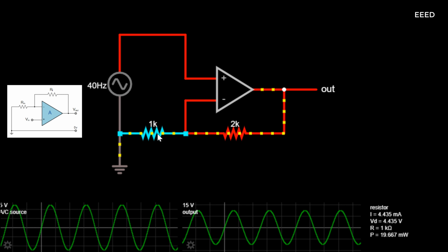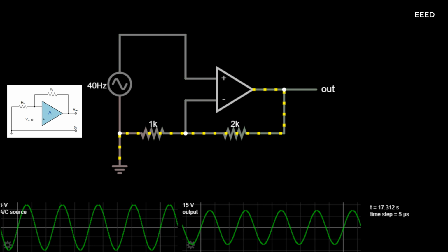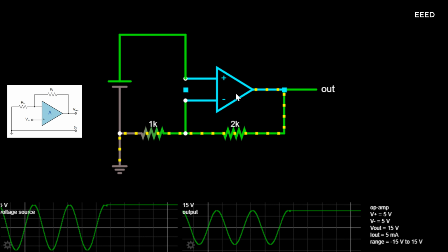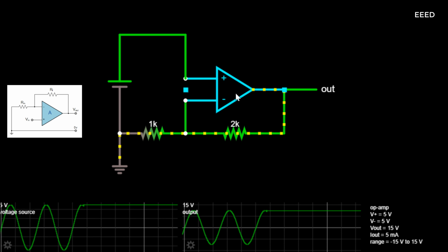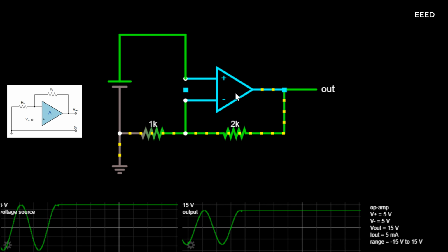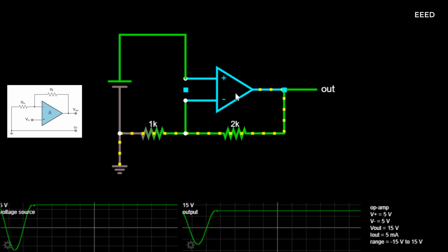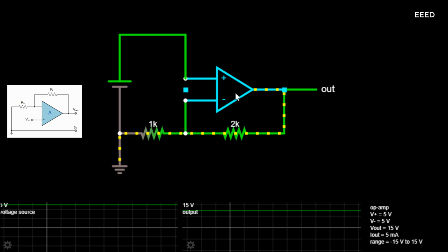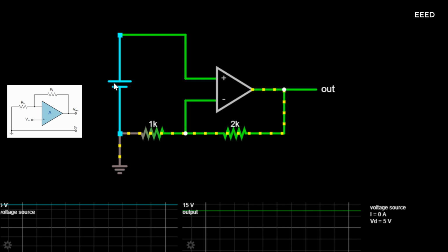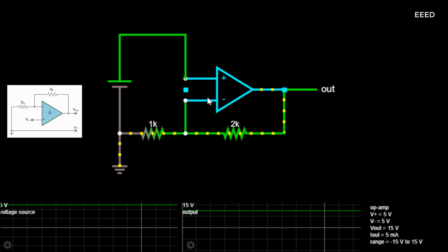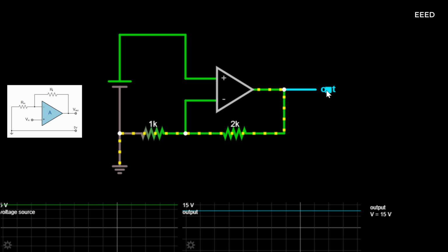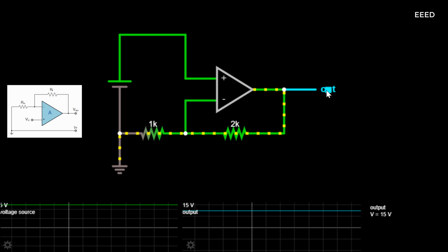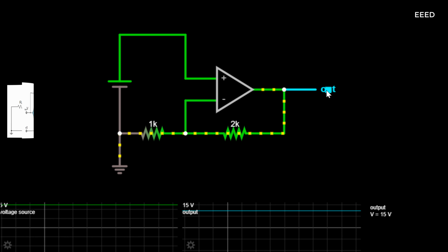This then makes the voltage follower circuit ideal as a unity gain buffer circuit because of its isolation properties. The advantage of the unity gain voltage follower is that it can be used when impedance matching or circuit isolation is more important than amplification, as it maintains the signal voltage. The input impedance of the voltage follower circuit is very high, typically above 1 MΩ, as it is equal to that of the operational amplifier's input resistance times its gain, RIN x AO. Also, its output impedance is very low since an ideal op-amp condition is assumed.